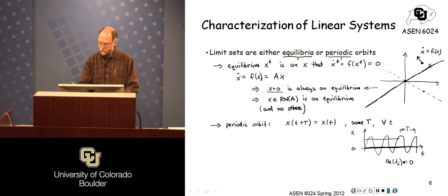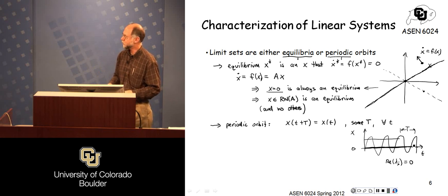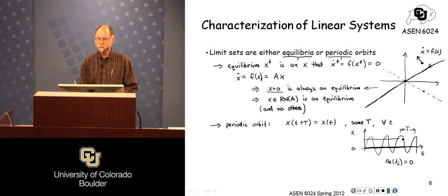And generally, you're not going to get a truly periodic solution unless you start with just the right initial conditions. And so particularly if we look at the similarity transformation that decouples everything, right? We could look at the initial conditions such that we have initial energy in this mode, but none of the other modes that might be decaying or growing. Okay? So in that case, we just have energy in this mode. It starts off in the right initial condition, and it just oscillates there with no decay or growth. That's really the only way you can get this periodic solution, but it is a solution to the differential equation for a particular initial condition. Okay?